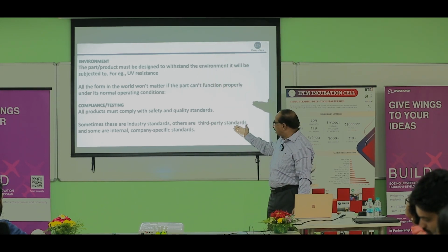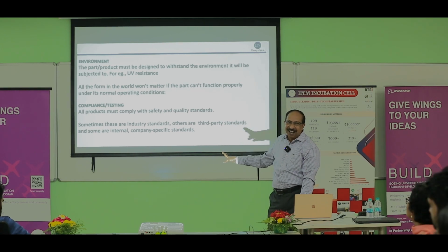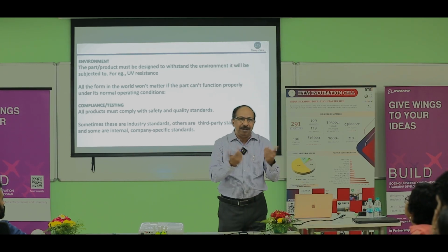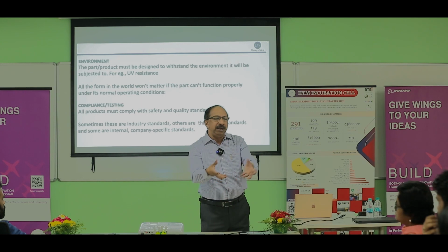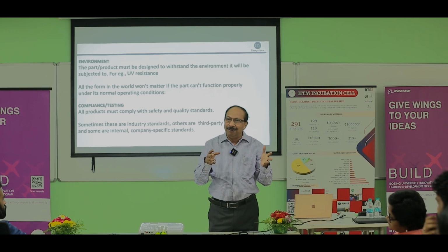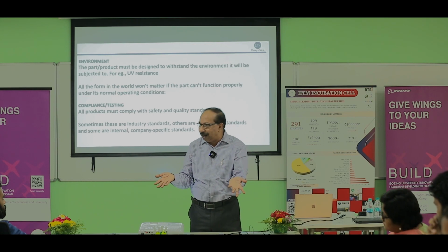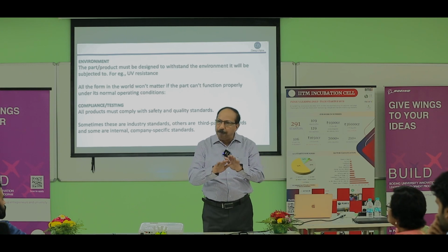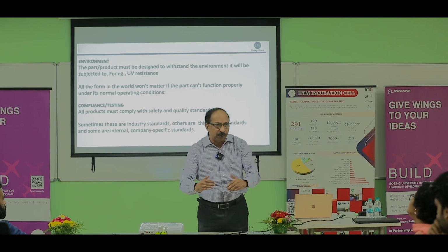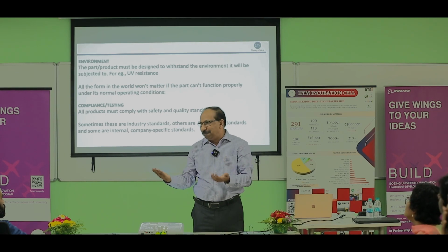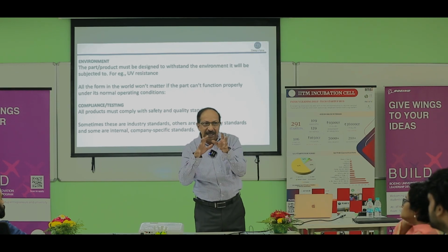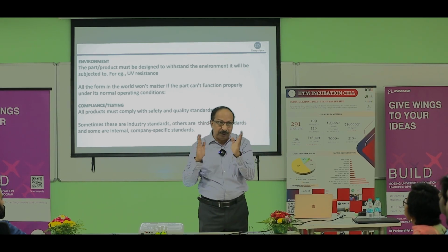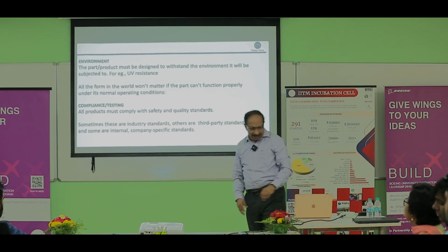Then compliance testing, this is one of the very, very difficult tasks. I always suggest this, as many startups came up with a final product and it doesn't pass the compliance test. At that time, whatever expertise you have, it is very difficult to make any changes. For example, if any radiation comes out, you can always probe it, but you have to put a metal sheet on it to suppress it so that it doesn't come out. But there will not be any space because the mechanical structure is already done. That's why I am saying these aspects must be taken care of at the design stage. It is not an afterthought. This is very important.